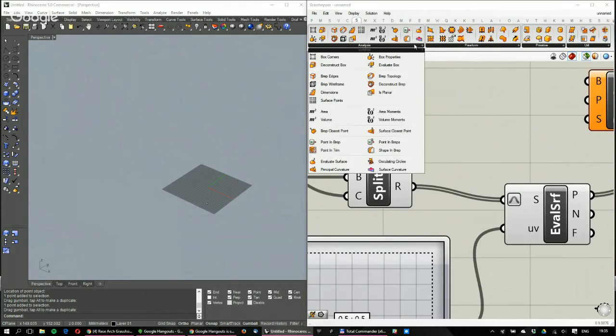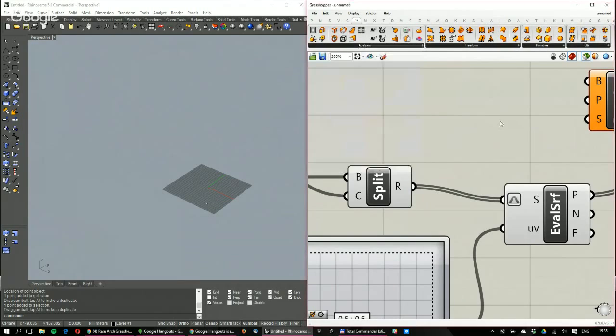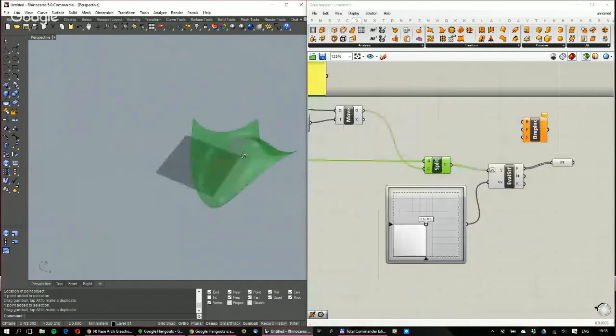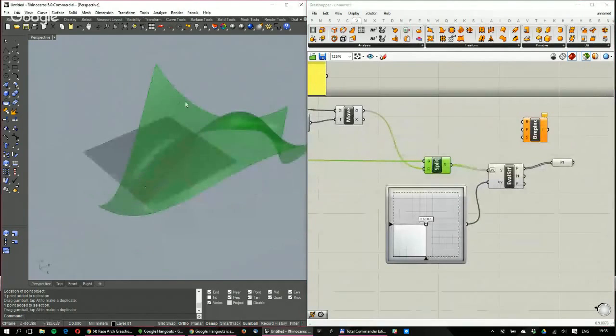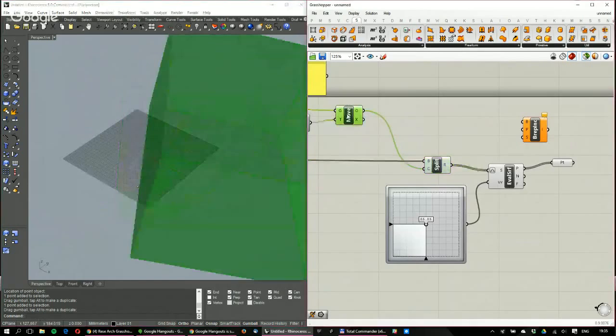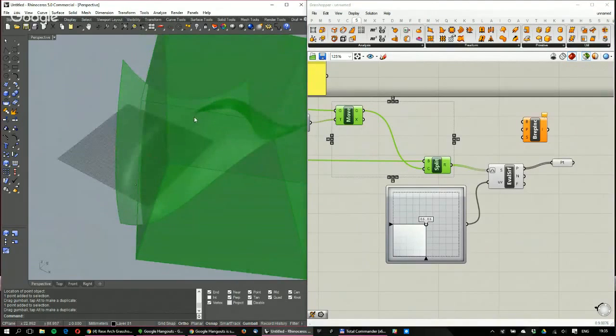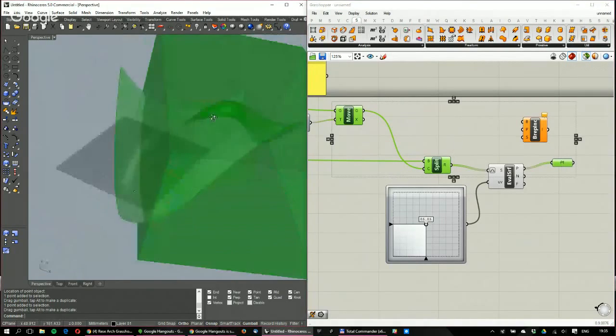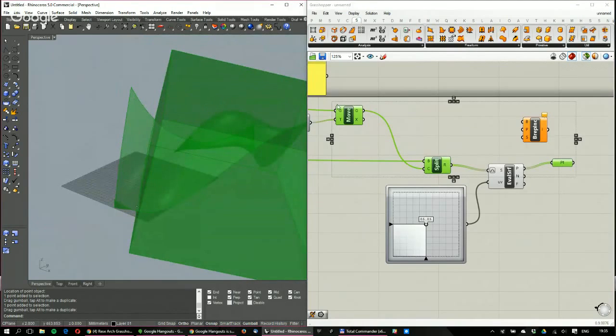or maybe basically the only thing that we need to find out is which surface has points inside of this bounding box. And the problem here is that if I evaluate each of these surfaces at their middle, the middle would be the same point because they are still the same surfaces, just trimmed differently. So I could either rebuild those surfaces so that they lose the original idea of what they were, or I can do it some other way.